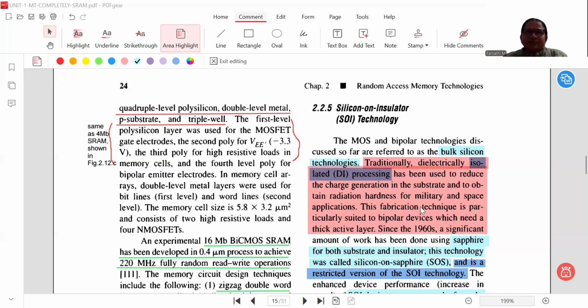Actually there is a problem called latch up. It was observed in CMOS technology. When a short circuit path is created over a period of application of voltage, from VSS to VDD, unnecessary current would flow from PMOS to NMOS. That current was not required apart from the required operation. So the actual operation will go erroneous in the case of CMOS technology.